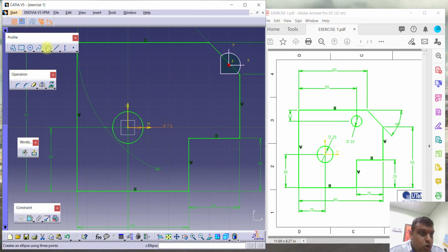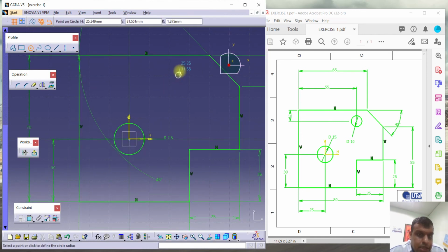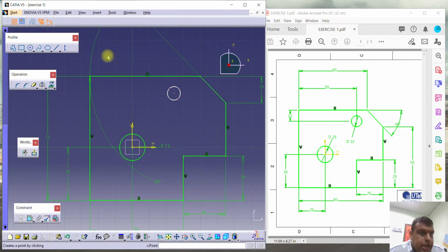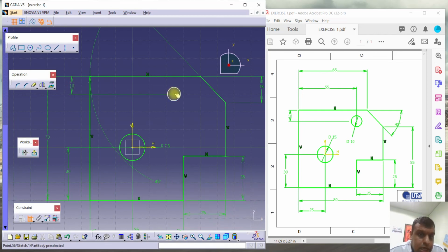7.5, and then you click one more circle. Just put it in this position, like this, and then you put a constraint. First, from this top to this center point, I double click because we use the constraint icon repeatedly. Here to here is not the right size yet. Here to here is 10. I just double click 10 mm. Here to this line is 55.